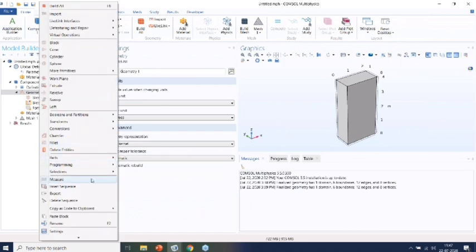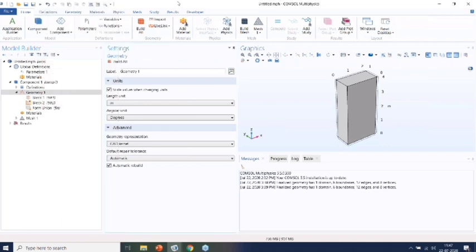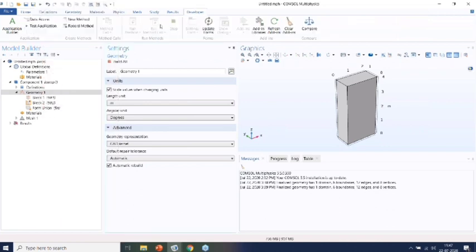Or else, there is something called the developer tab, which is also available. This is a little advanced, but here we have some COMSOL blogs. I would request my colleague Uttam to share those blogs with you, on how you can automate the model building processes in COMSOL. By using this developer tab, you can actually record code to create a certain geometry part.